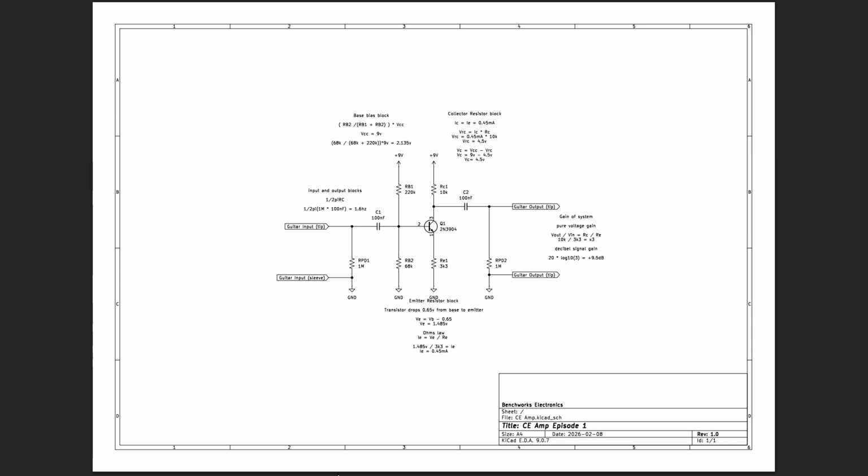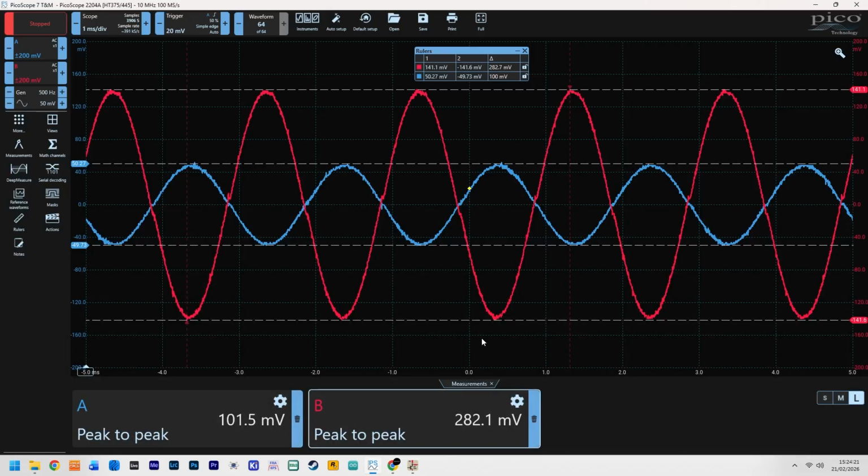And if we just jump back to the oscilloscope here, just to round that off, our unit 1 coming in is about a unit 2.8, 2.9 coming out, which is perfectly within our spec and proves that the math does work, and that sometimes you just have to adjust some of the math for your actual components. For our circuit, we just needed it to be within the ballpark of what we designed it for, because we're going to end up distorting this with diodes next week.